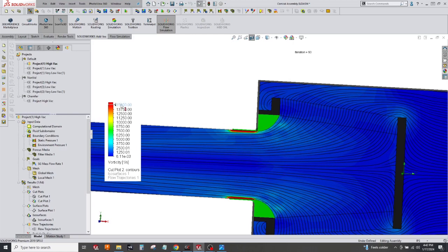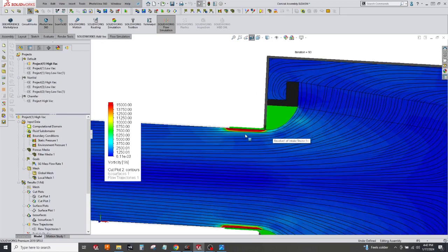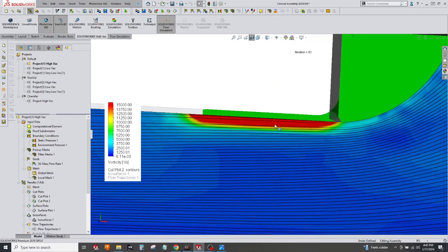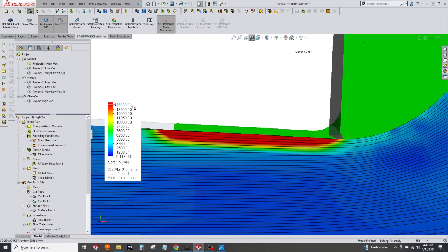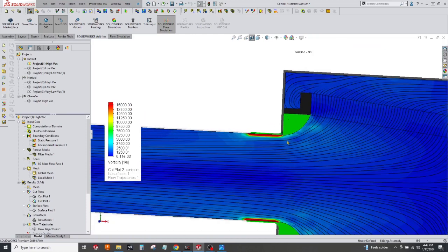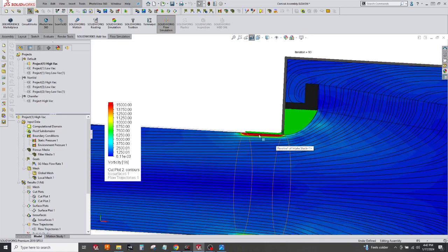And if we use that same value, we can see that those numbers are drastically reduced. The region that's affected by that is very insignificant, but it is still here. If we zoom in on this a little bit more, we don't see the turbulence necessarily, at least in the flow lines, but because we are still seeing that higher number there, this would definitely tell me that we could probably optimize this geometry a little bit better and maybe get a little bit more flow out of it. And this is the tool that I would probably use for going through and optimizing that geometry.